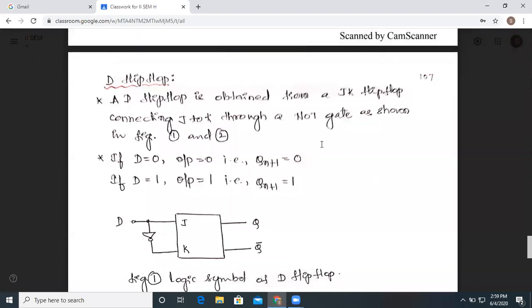In the previous few sessions, we have been discussing flip-flops and latches. We already know that there is a small difference between latches and flip-flops. Latches and flip-flops are going to store one bit of information. These are called storage elements. But there is a slight difference. Latches generally have asynchronous inputs, but flip-flops have synchronous inputs. Latches are level triggered and flip-flops are edge triggered.